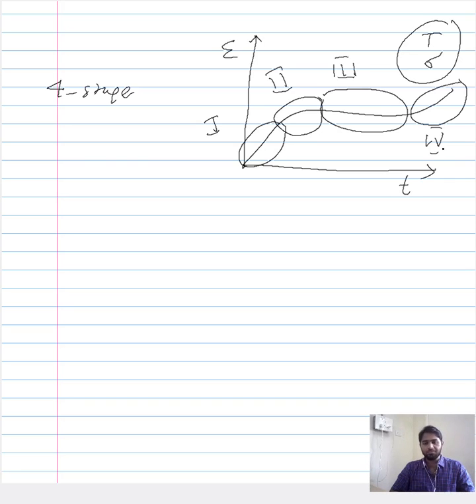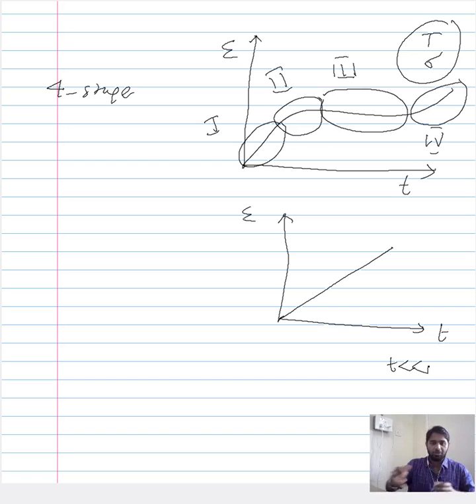Now in this lecture, let us try to see what are the factors that are responsible for these creep curves. Let us begin by taking a phenomenological approach, and by considering the instantaneous creep. The instantaneous creep involves the strain exhibited by the material once you start applying the load. So this is your strain at the time t, and this time is close to 0, very small when you compare it to the overall time taken for the creep testing.